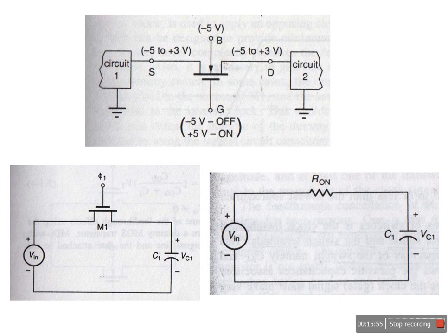Okay, so this is the point we should consider, that what will be the voltages at the terminals. So it cannot make it up to the 5 volt. The reason is, at that point where VGS will be equal to VT or less than VT, the transistor will go off. Okay,